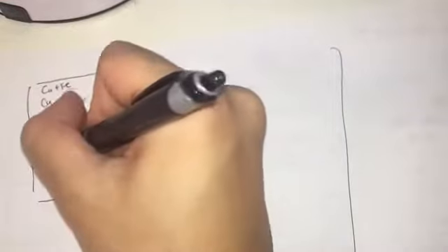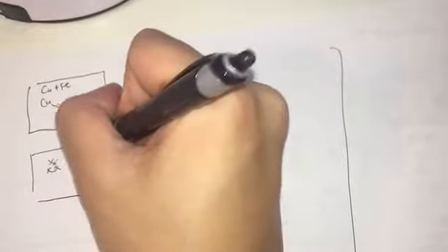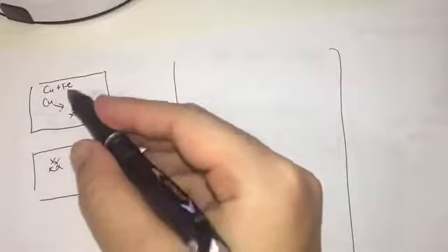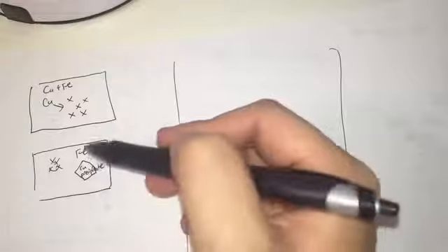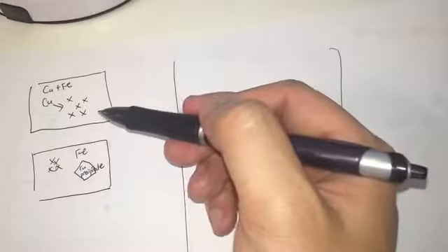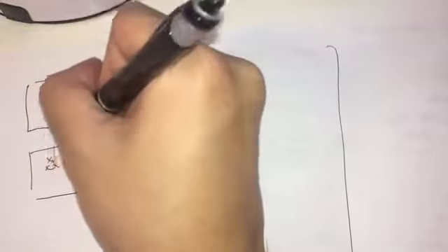So these vacancies will be moving elsewhere, the rest of it will be iron, but the copper will move into this precipitate here, where it's more thermodynamically stable, and this region will be copper depleted.